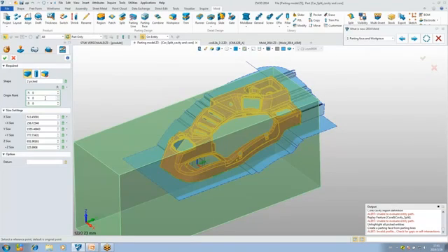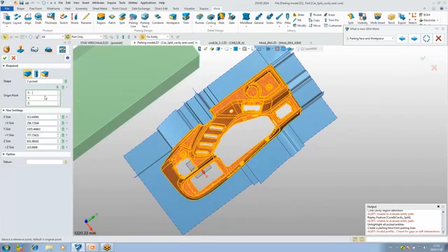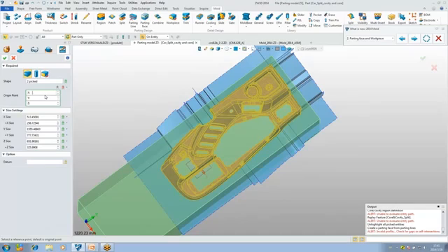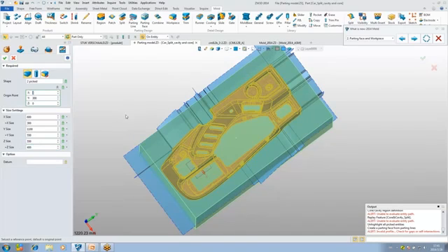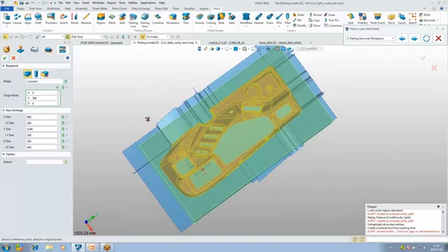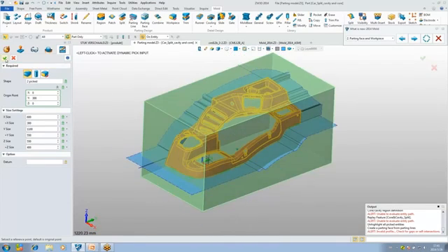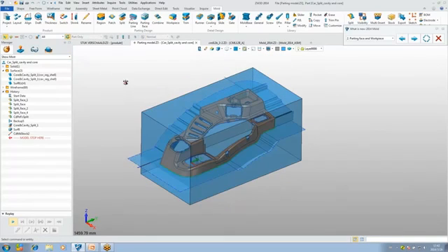Here, let us define the origin point. And if you don't set the origin point, it will use the yellow point as the origin point. Set it to 300. And set the workpiece size for the X, Y, Z direction. Just input the value directly, so you don't need to create a sketch each time. Just click OK. So we can easily create a workpiece in the new ZW3D version.